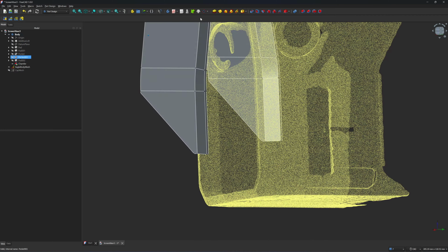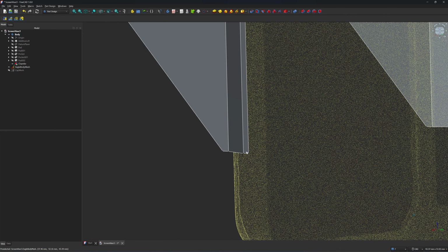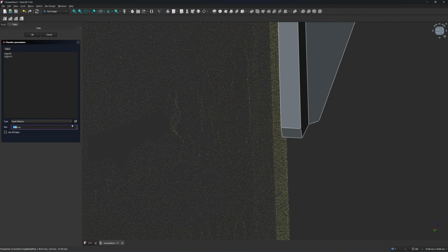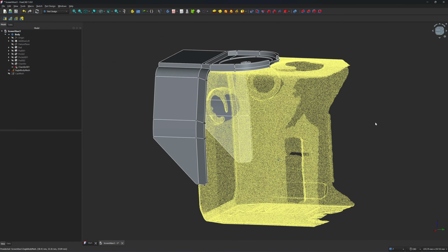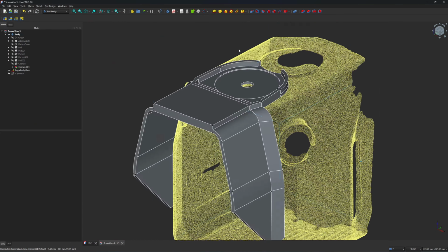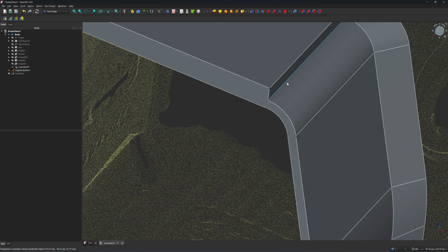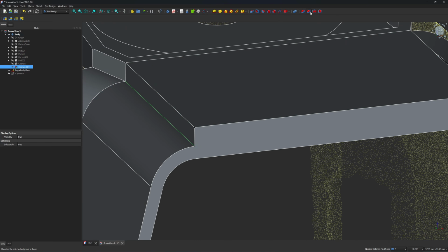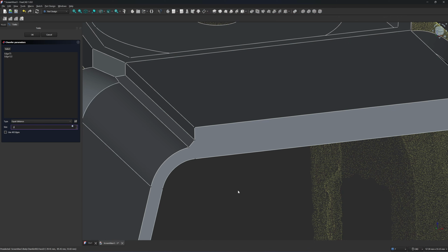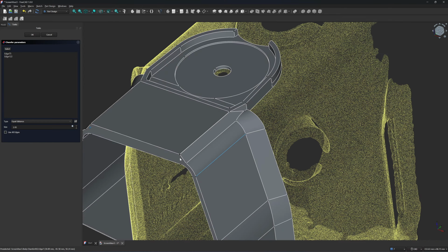Okay, let's do some more chamfer in this corner. And 2 millimeter. Okay, and then I'm going to make another chamfer here on this edge. Click on chamfer. Let's try 3 millimeter. Cannot do. 2.4, right? That's weird. It should do, right? 2.9. Can I do 3? 3 cannot do. Only can do 2.95. Yeah, it's quite strange. It should be able to do this.